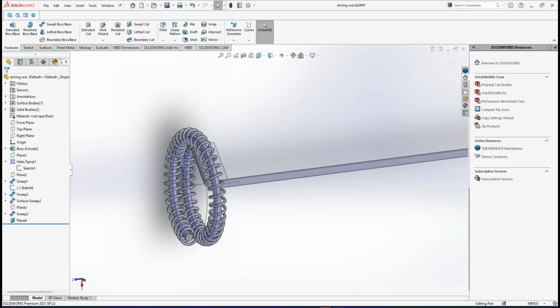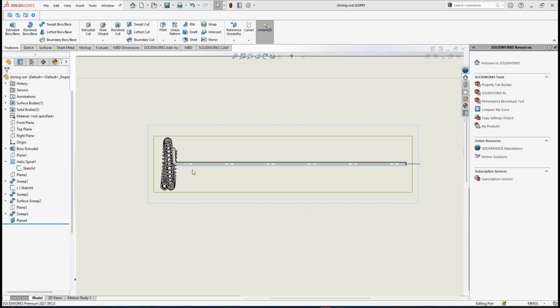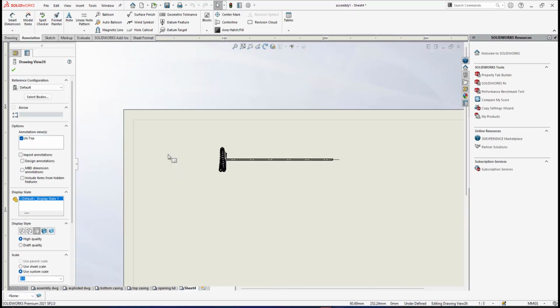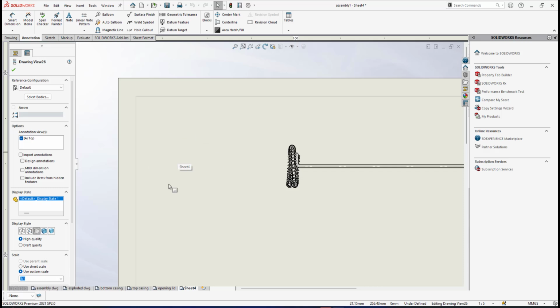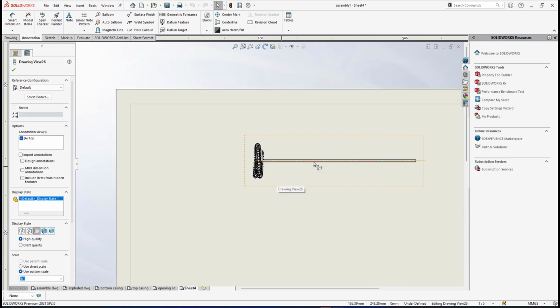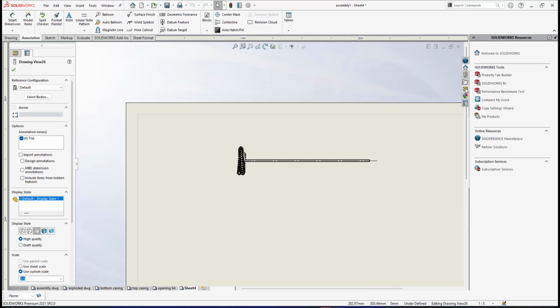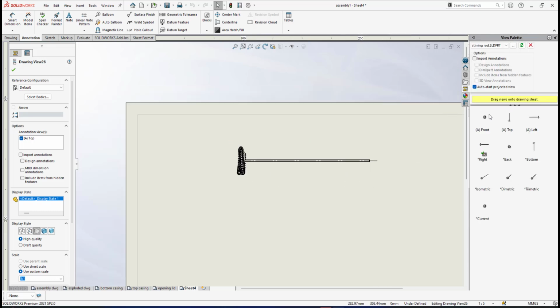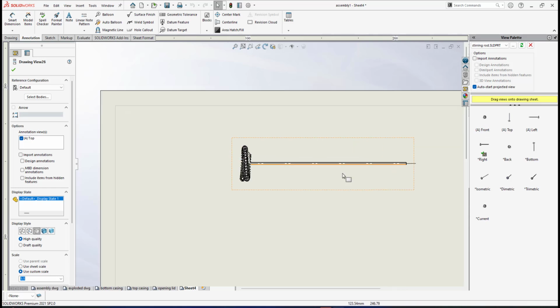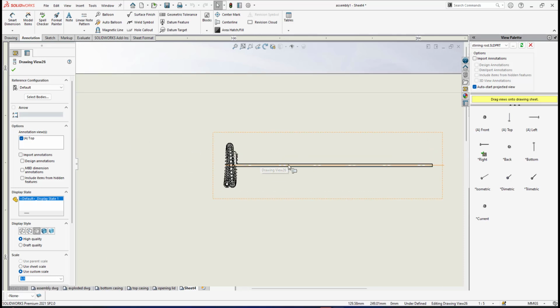If I go back to the drawing mode, the idea is that I want to make this left view here, and it can show the base circle, then I can put the dimension for the base circle, which is diameter 20, right? To make this left view, I can go to the view palette, but sometimes I'm not sure which view is really related to this side view or this top view.